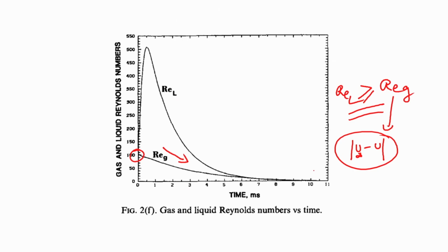with time. The liquid phase Reynolds number, however, shows slightly different characteristics. It initially goes up and then it comes down. Can you imagine why? The liquid phase Reynolds number will go up because when the droplet is accelerated, this is a function of us, the surface velocity, and if you recall, the surface velocity was a function of Cf, the Reynolds number and all those things, a function of the delta u.